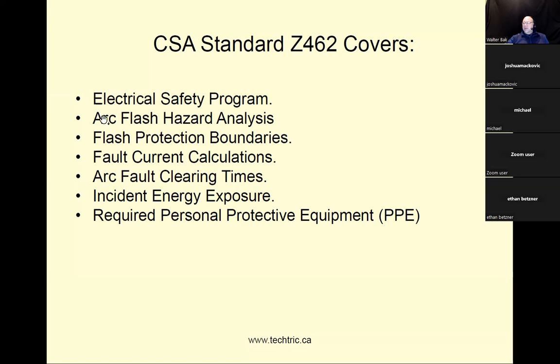Electrical safety covers the electrical safety program, arc flash hazard analysis, flash protection boundaries. We're going to talk about those. Fault current calculations, and this has something to do with how much current can be provided at the point of the arc flash under dead short conditions.